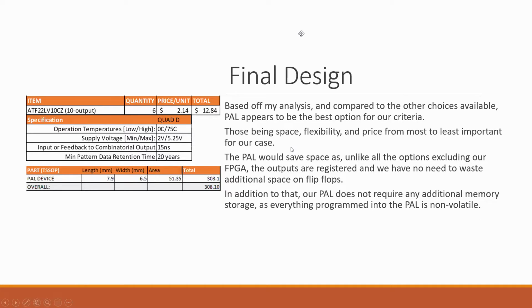The PAL would also save us space on the D flip-flops since they're going to be registered output, so we don't have to worry about our flip-flops. It'd be the same sort of thing with FPGA, but I didn't want to worry about the fact that you have to pair that with memory. And that's my final design. Any questions?